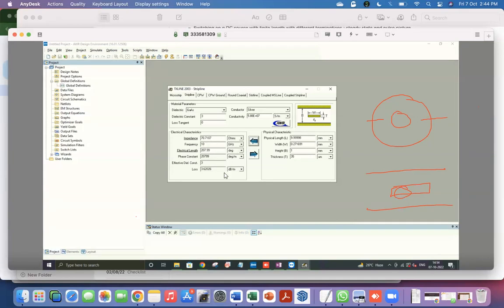But just so that you're not confused by what's going on with this number, we also saw what happens when you have field lines in both air and dielectric. Then you get some effective number here, which is smaller than the true dielectric constant of the main dielectric in the system. But obviously, there's nothing called a main dielectric. There is a substrate on which you have to design these things. And if the structure of the transmission line is such that the field lines have to exist in air, then you have to take that into account.